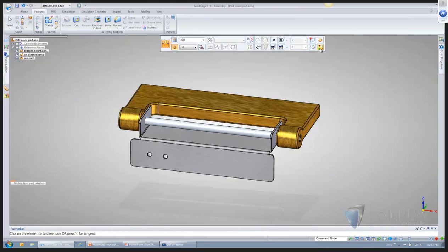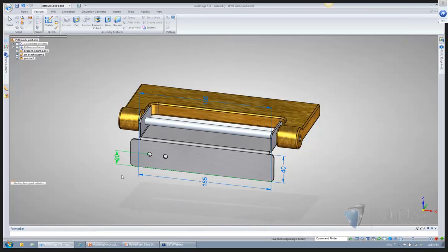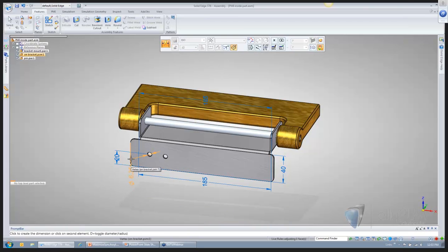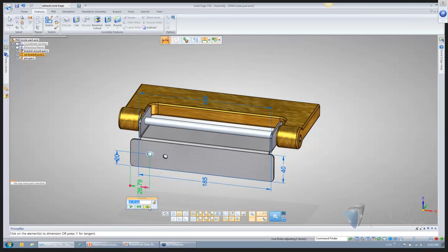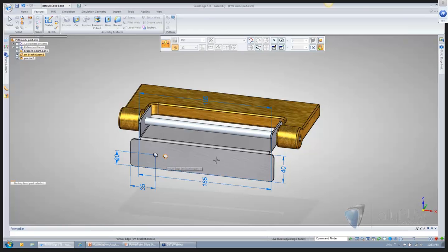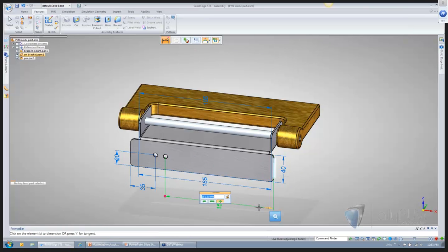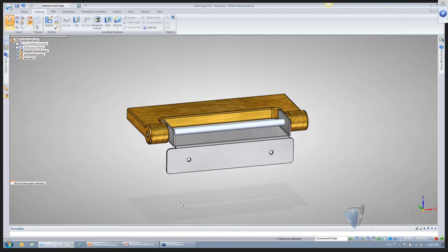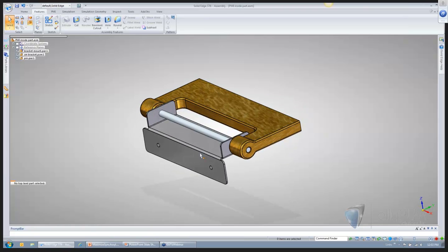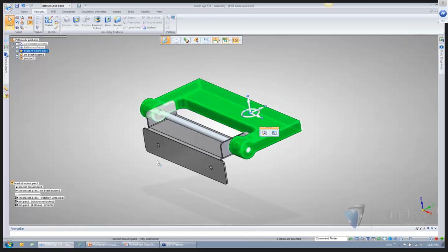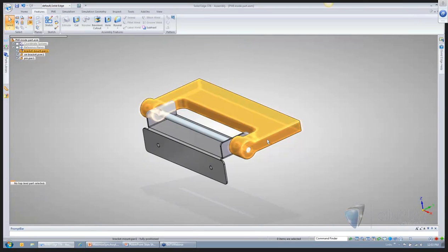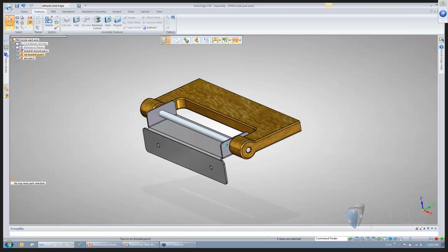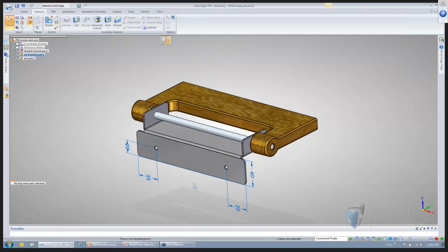So I'm going to come back up in here and say I need a PMI between these holes, and these guys should be 20 millimeters. And since I'm still in the command and the option is still set, I want to actually drive these from the outside edge in 35 millimeters. So we can do all this part level design intent at the assembly level, place in assembly features at the part level, and modify our part. So if I go to part priority, I'm simply getting the parts here. But the beauty of having face priority selection is that any face we select that has dimensions associated with it, we're going to be exposed those dimensions via the PMI from the assembly environment.